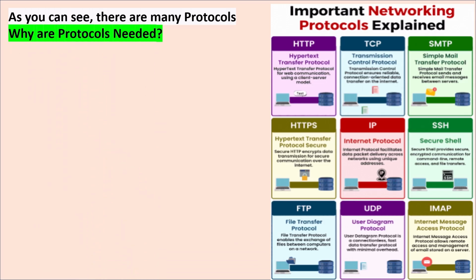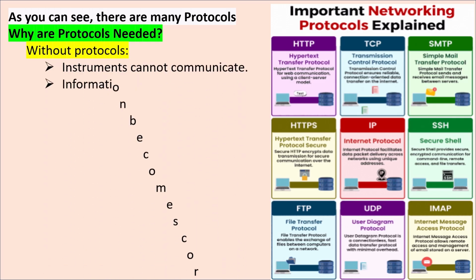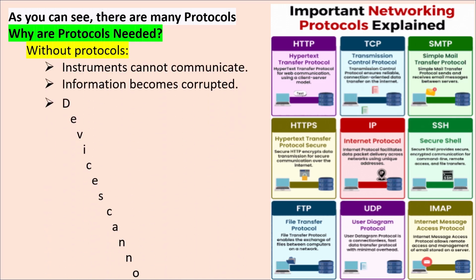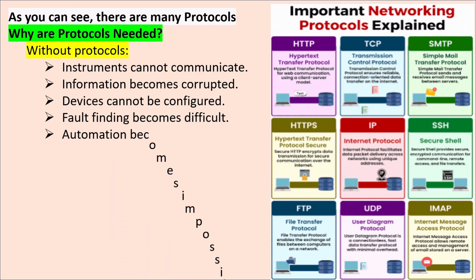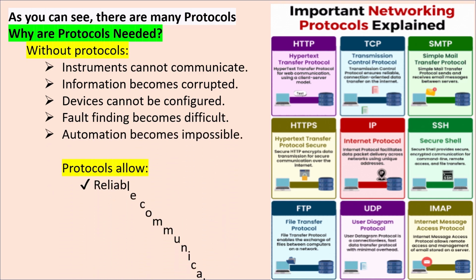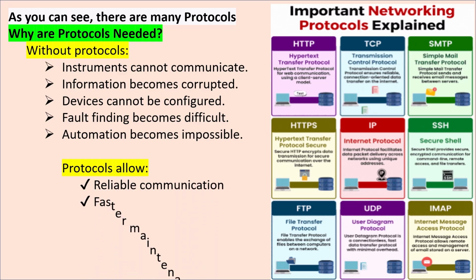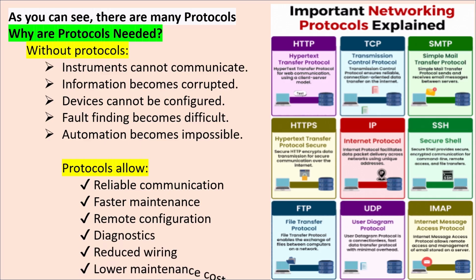Why are protocols needed? Without protocols, instruments cannot communicate. Information becomes corrupted. Devices cannot be configured. Fault finding becomes difficult. Automation becomes impossible. Protocols allow reliable communication, faster maintenance, remote configuration, diagnostics, reduced wiring, lower maintenance costs.